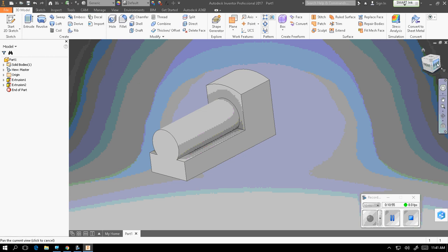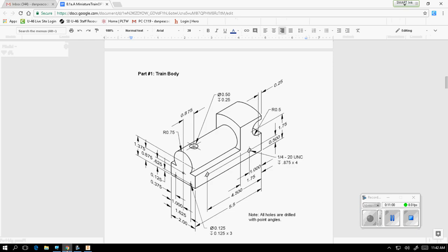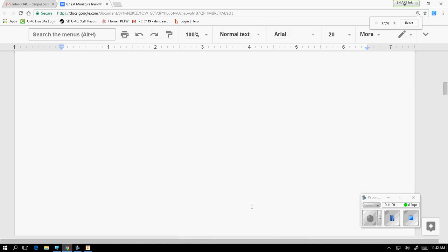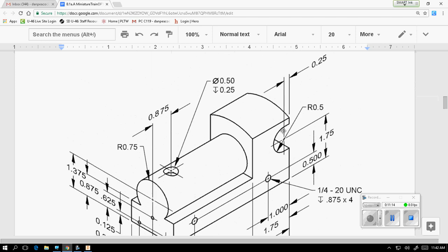Let's start with this back portion here, okay? When we look at this, we want to create this, okay? But notice, if I make this a little bit bigger, these lines here are straight. They don't arc down. So what we want to do is create a circle, and then make lines that are tangent to that circle that make a flat surface so it's not curving down, okay?